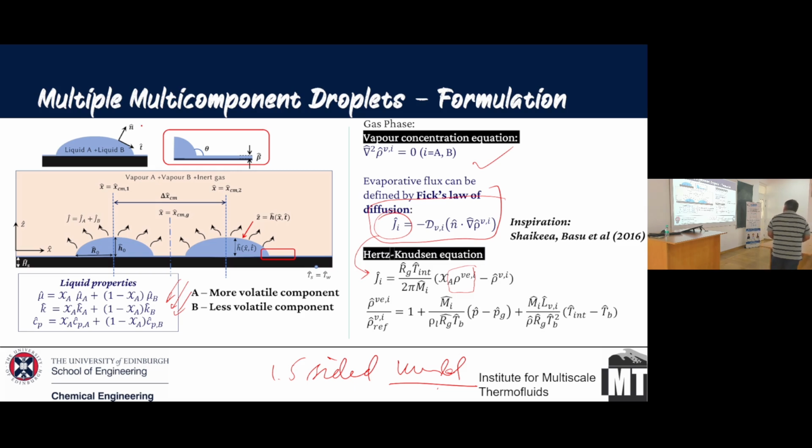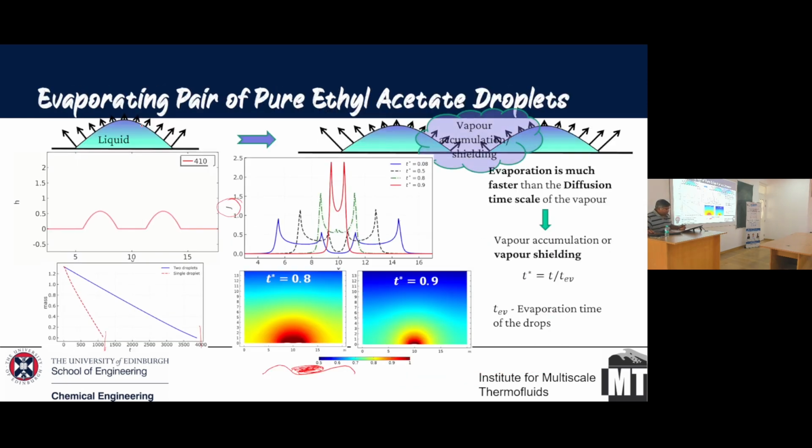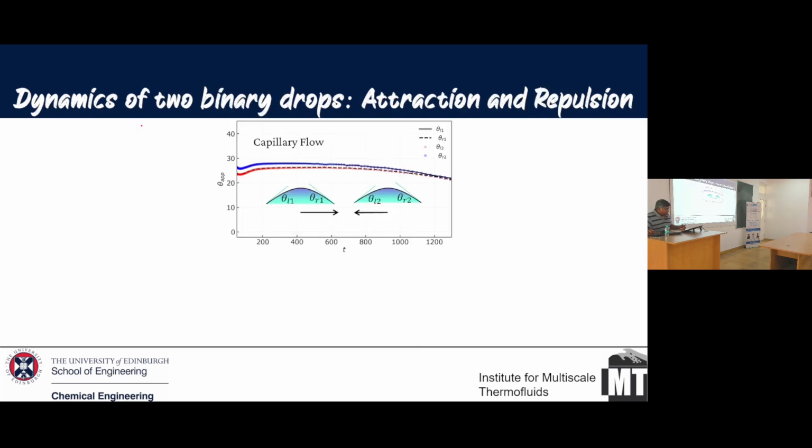And these are heavily pinned contact lines? The simulations I'll show tomorrow are pinned, but these, if you look at the experiments, move. Here, because there's a precursor film, there is no restriction. You will also see the way contact angle changes with time here. He also has a velocity plot. What are the contact line velocities? I have not shown it here, but you will see that these are moving contact lines.